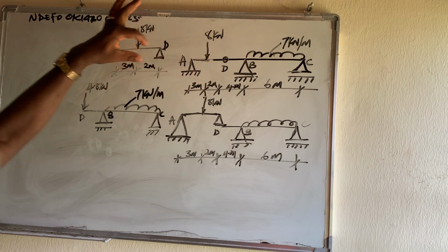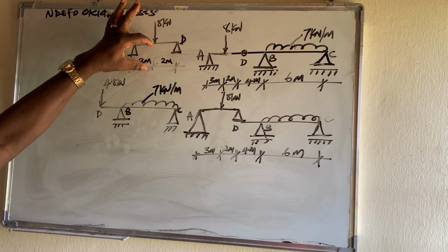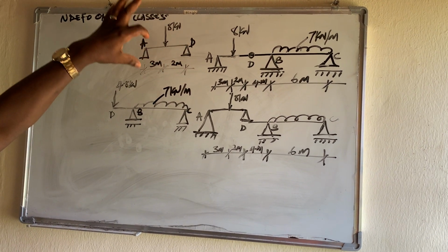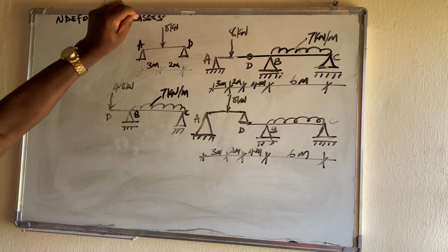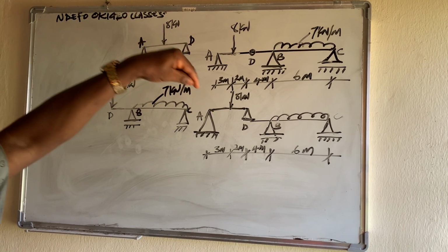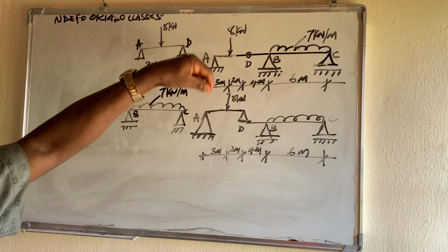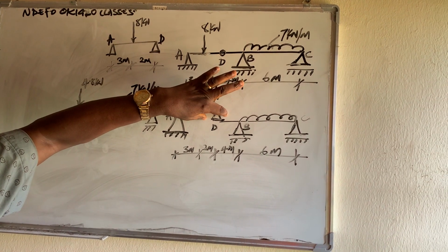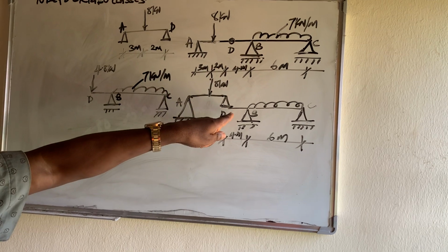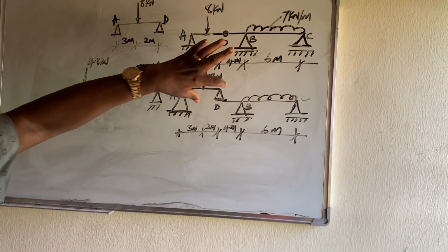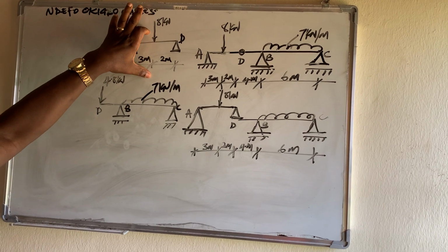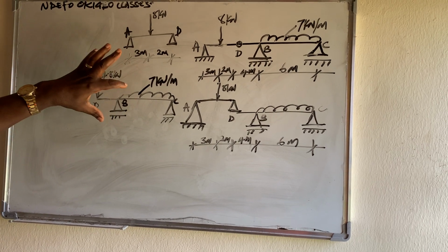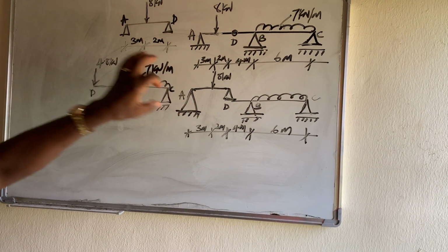So that's why we now cut the beam and get this small beam AD with the same load. We solve the beam AD first. After solving it, the reaction at D will be loaded on the beam at point D. That is AD broken. The reaction at D is rested on the beam at point D. When we analyze this beam, we get that reaction. You will see how I got it, 4.8. So I brought it onto the next beam, that is beam BC at point D.